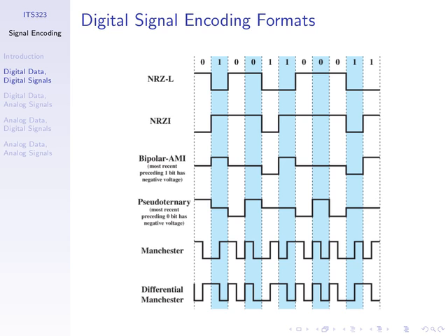Again, with non-return to zero level, I'll draw a receive signal. It's not related to what we have here. There's 1, 2, 3, 4, 5, 6, 7 pulses. And now using bipolar AMI, I'll draw an example receive signal. In fact, we have 3 levels.